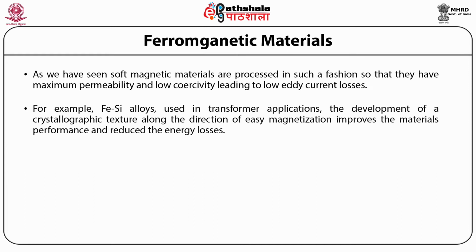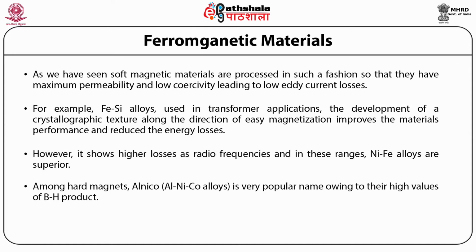For example, in iron silicon alloys which are used in transformer applications, the development of a crystallographic texture along the direction of easy magnetization improves the material's performance and reduces the energy losses. However, it shows higher losses at radio frequencies, and in these ranges nickel-iron alloys are superior.